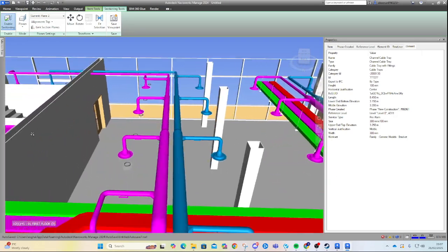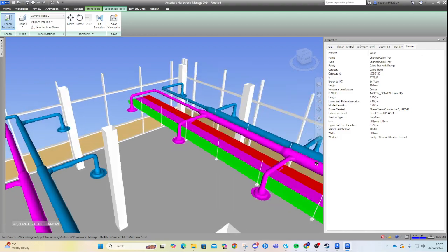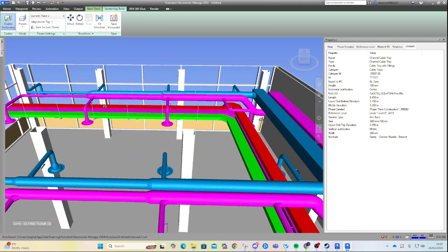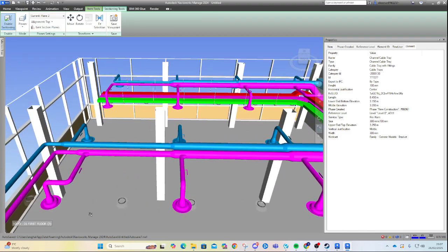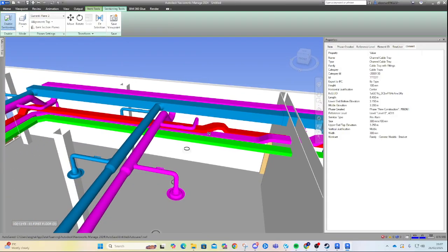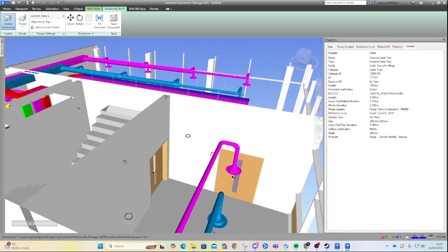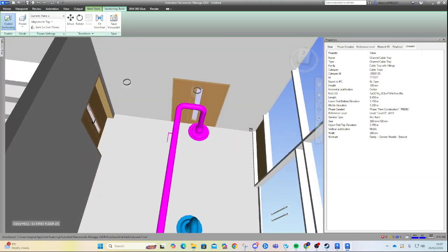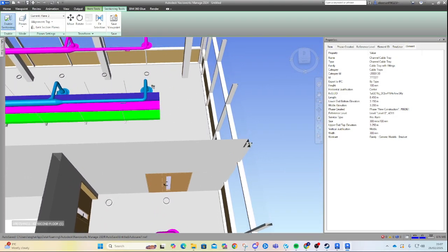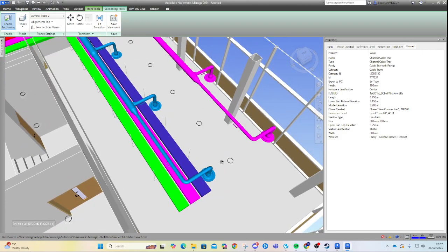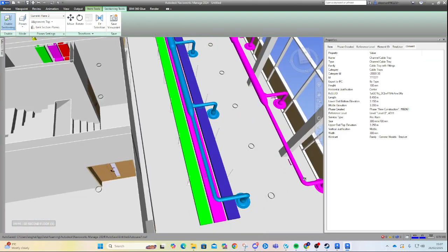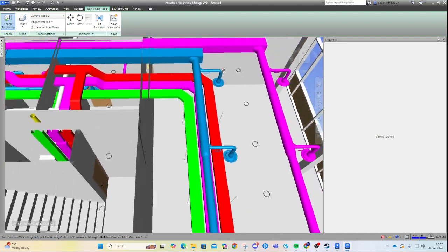Should we be following the ductwork? Should we have a branch over here? How are we going to get from here to these lights, for example? So we should have another one coming down here servicing these lights, because we're obviously going to have lights and smoke heads in that room. We've nothing in here, so it's easy to see in areas. How do you get to the lights? We're probably okay here, but we're not okay everywhere.